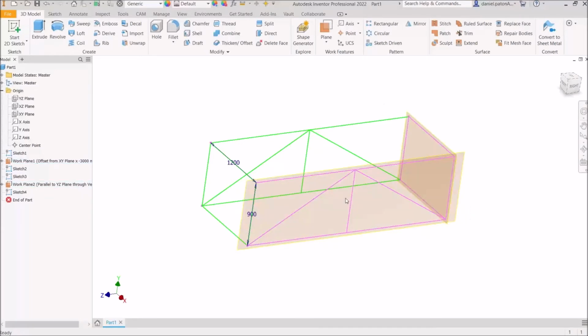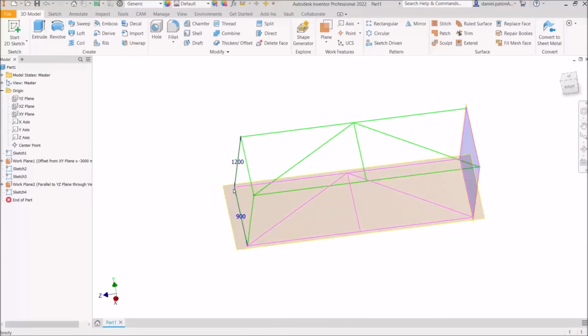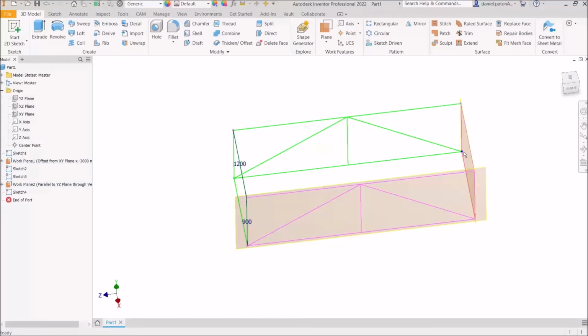If you want to make this a lot more complex, you can, and you can just continue building more and more sketches. If you want to combine some 2D sketches as well as 3D sketches to make your designs a bit more complex, you can, especially if you need to add any sort of diagonals from one corner here to the opposite corner there. You can very easily take a 3D sketch and just basically create a line between those 2 points.